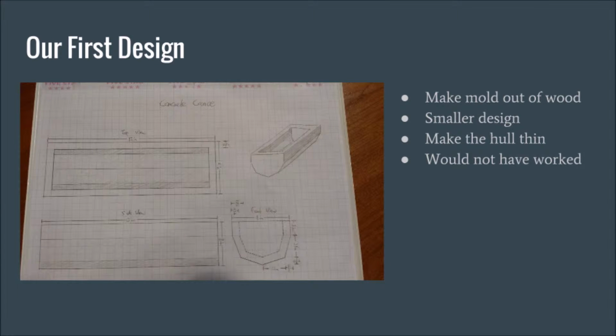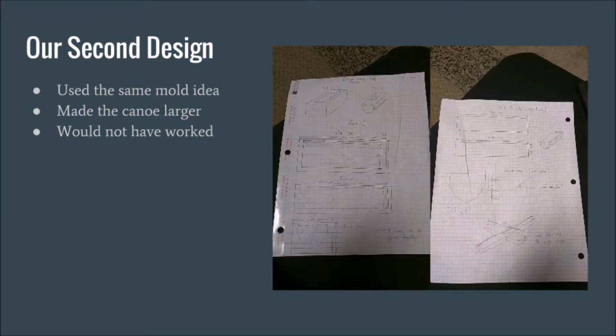In the engineering design cycle, steps 5 through 8 are repeated through several designs until a finalized design is complete. After analyzing several potential solutions, we drew up our design and then gathered our materials. During the week or so while we gathered materials, we tweaked the design because we found that a larger canoe would create more buoyancy force per amount of concrete used, and so we made our canoe as large as the dimensions would allow.